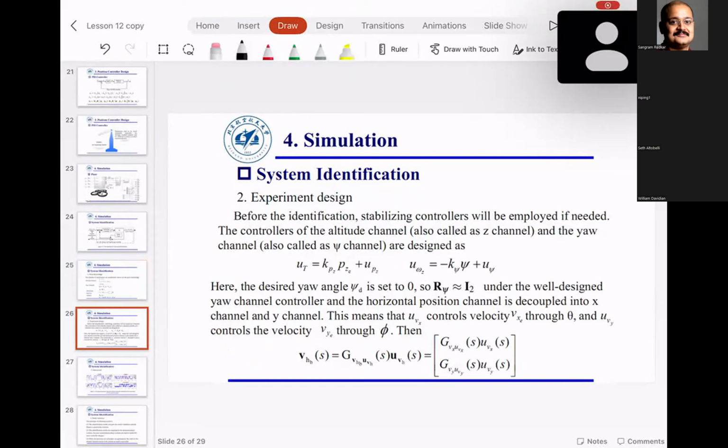One is model-based design, wherein you start with a mathematical model and use that model to design. The other is experiment-based design, which means once you have the system built, you perform a series of experiments and then refine the underlying model. When you go to industry, these two approaches are used simultaneously. You start with an underlying model, design the controller, implement the controller on actual hardware, perform lots and lots of experiments, make sure the controller works, and then move forward.